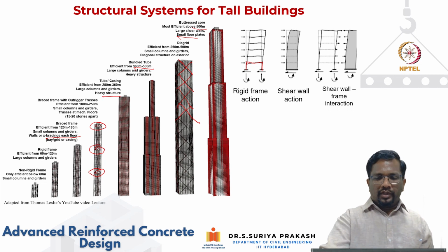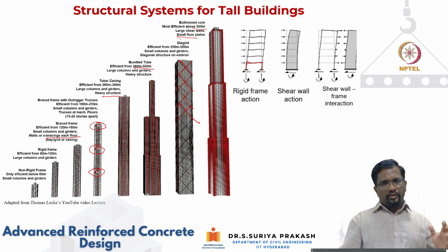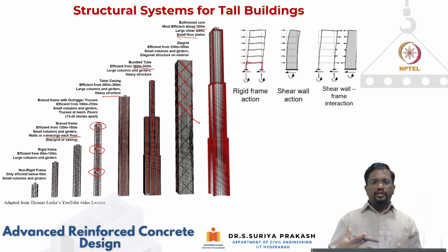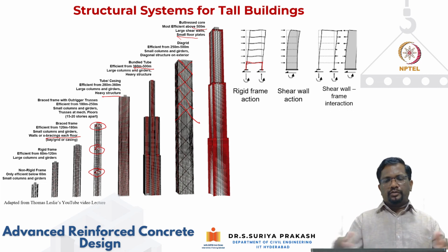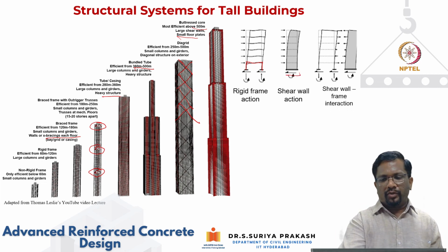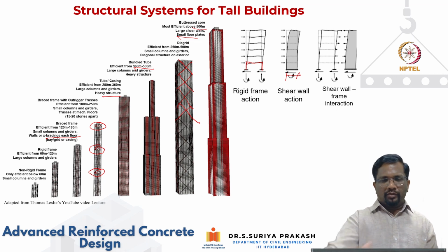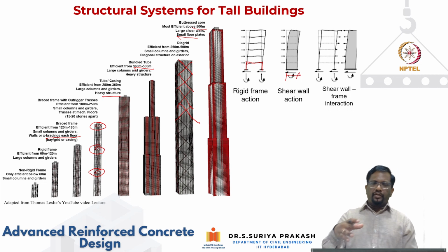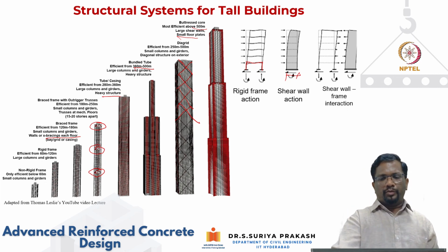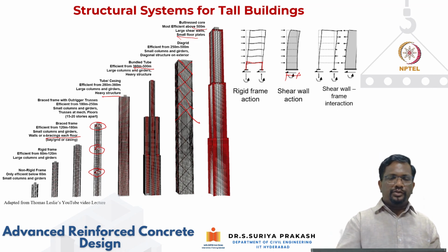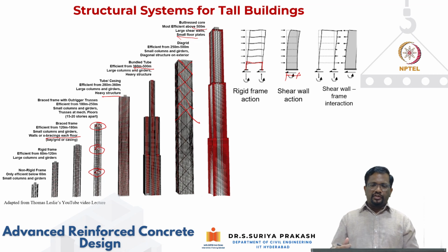Now, along with that, you also have shear walls. Shear walls, as I said, the lateral rigidity is going to be very high because the width of the wall is going to be quite large, right? And the moment of inertia, if the wall is going to bend like a cantilever, and we know that the moment of inertia will be large if the depth of the member is large, right? So in this way, again, we can resist a huge amount of lateral force by putting in the shear walls.